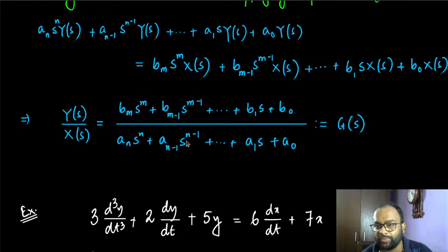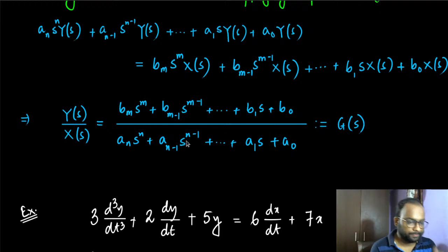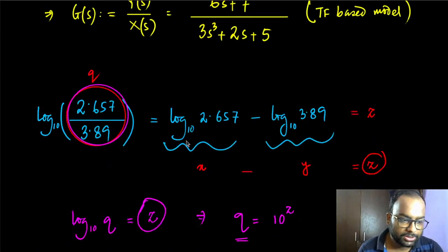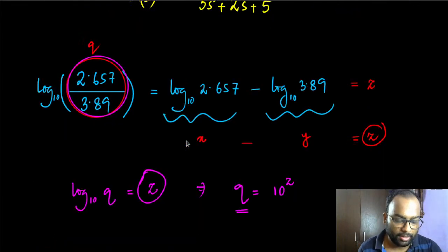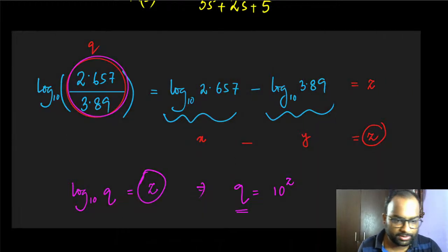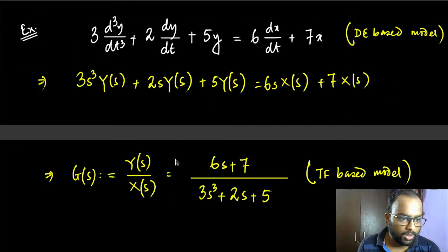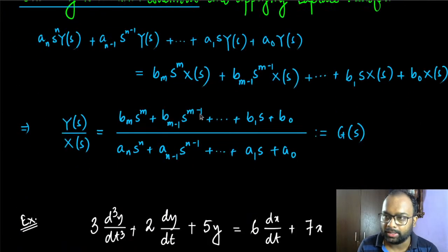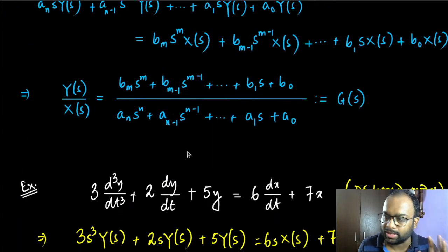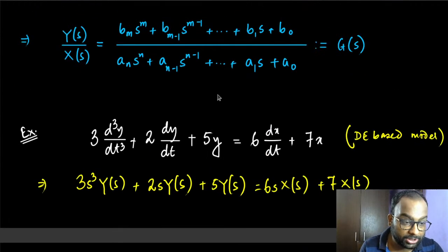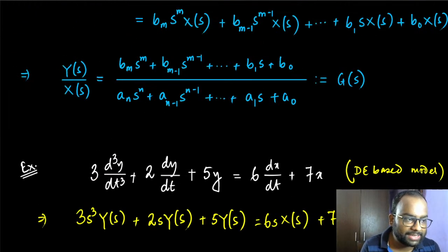So the transforms actually convert differential equations into algebraic equations, and that's how they got their names. That's how they are called transforms, the original names. All right. So I think that actually clears up a very important notion here. So get rid of this, not needed. All right, so let's talk about a few more important concepts regarding this, and then we're going to close this discussion. Okay, so this is the standardized transfer function here.